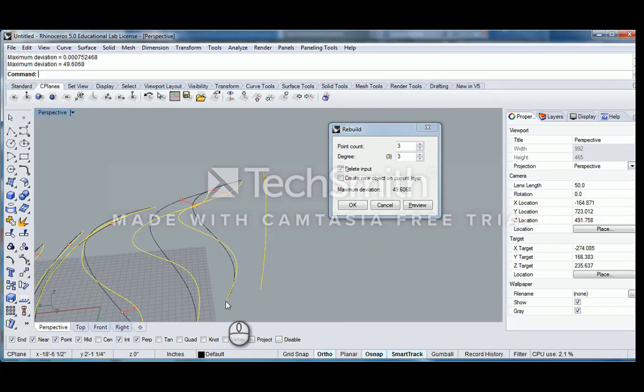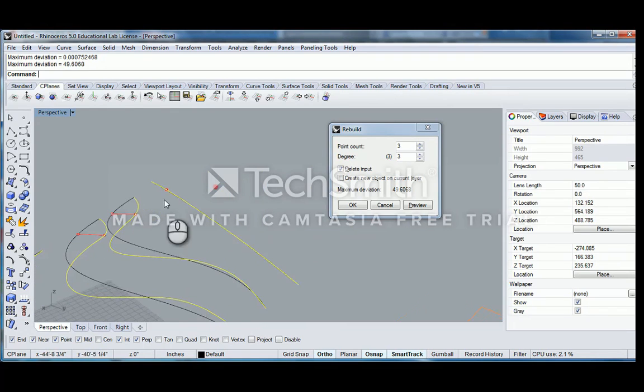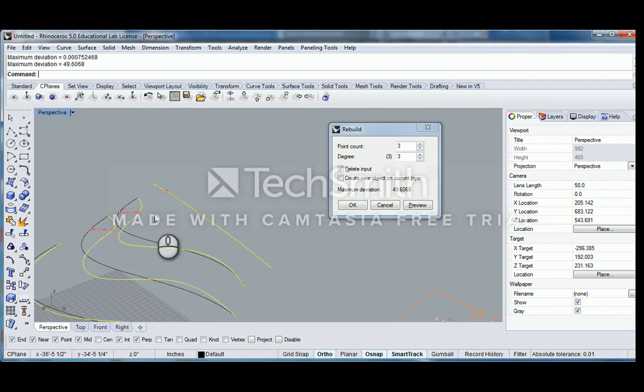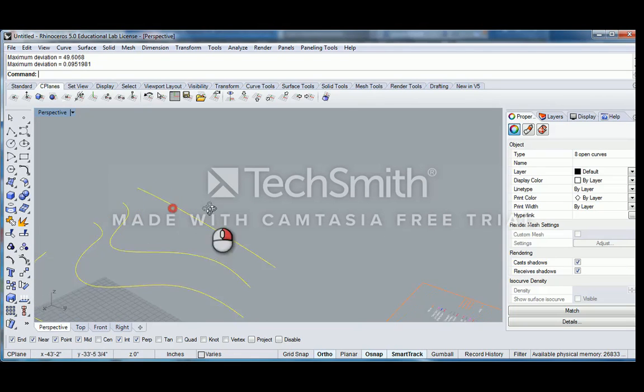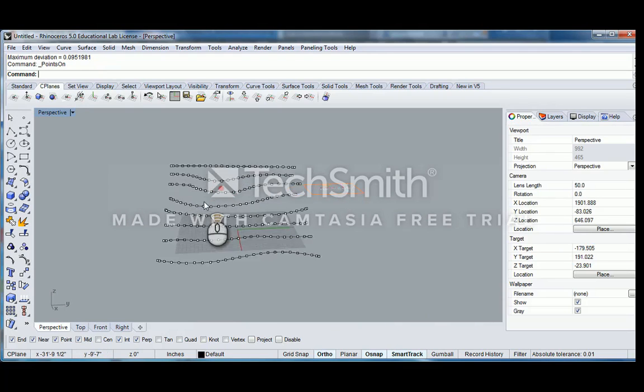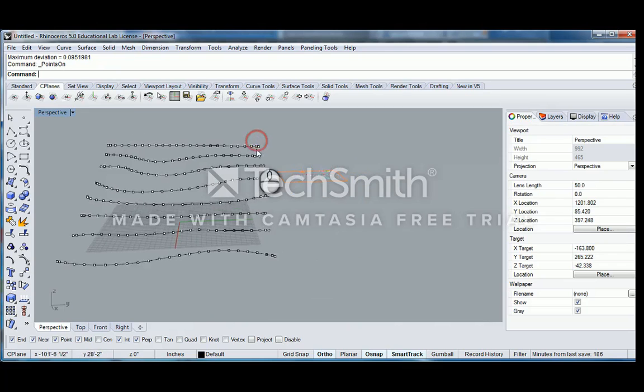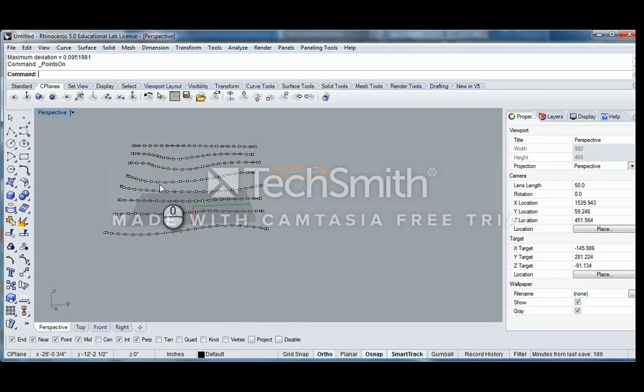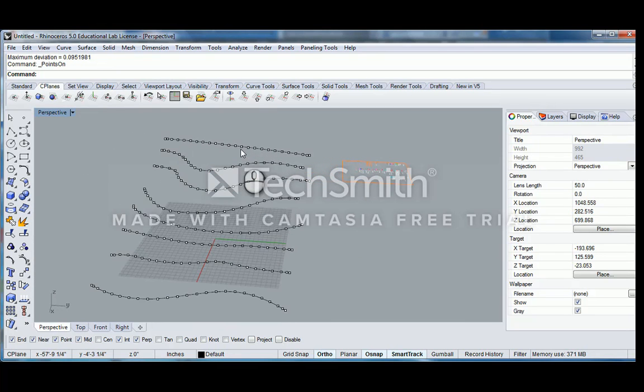It's drawing through an endpoint, and then one point in the middle, essentially, that it's pulling, right? So let's say that each of these lines, just so that they're all consistent, have 25 control points. So now if we turn points on, F10, all these are more or less equal in terms of the number of lines that they have. And it's just a little bit cleaner. If you wanted to do different points for each line, you would just click on each one.